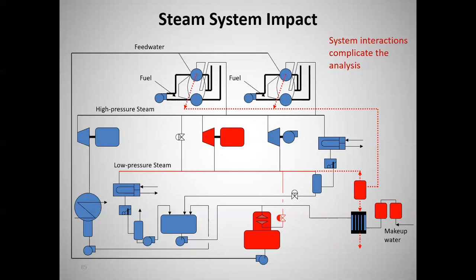So if I'm generating electricity, you see up here, I'm coming out. That's my saturated liquid at the drum pressure. I come down here, 23% of this stream goes into steam, and it goes directly into the header. So that amount of steam didn't come through this turbine. If that amount of steam didn't come through this turbine, it's not going to produce as much work. There ain't any doubt about that. So this output is going to fall based on doing this recovery.